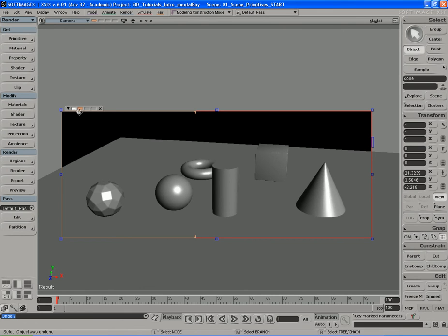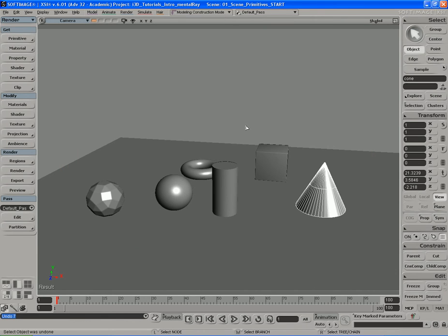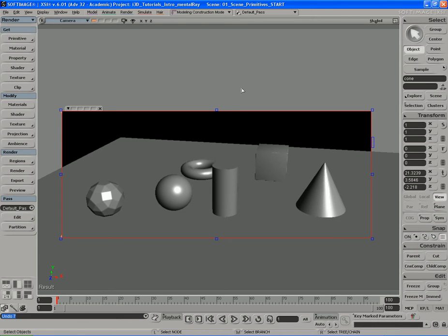Now what I can do is simply go ahead and right click, hit clear comparison image to delete that, and clear comparison image to delete that one as well. If you want to get rid of your render region right here that we drew out, just hit this little black X right there and it'll get rid of it for you. If you want to bring out the same render region without drawing a new one, what you can do is hit the Q button to switch over to the render region tool mode, which is the shortcut, remember, and go ahead and hit the middle mouse button and that'll bring the render region tool back up.